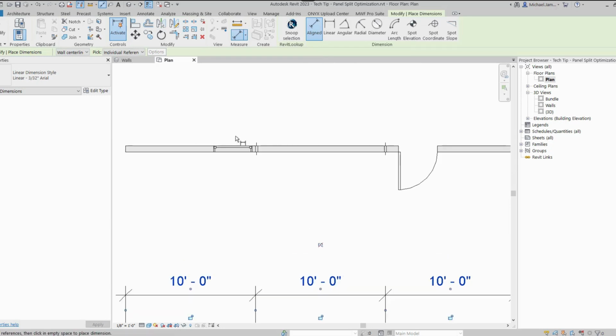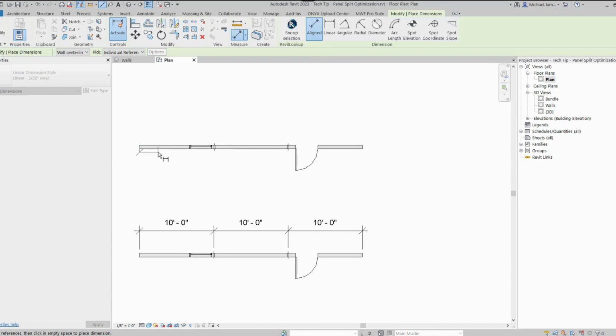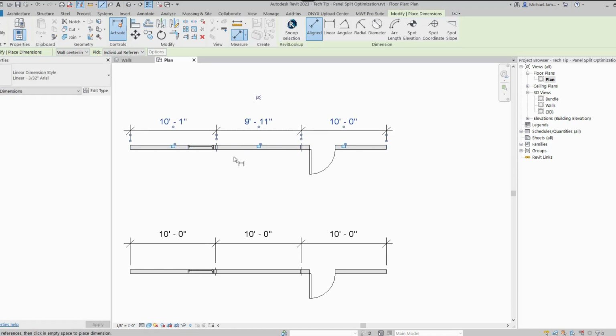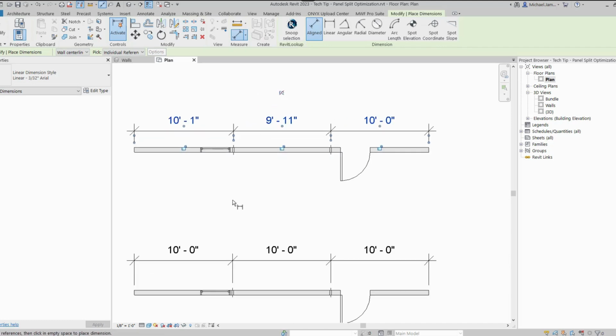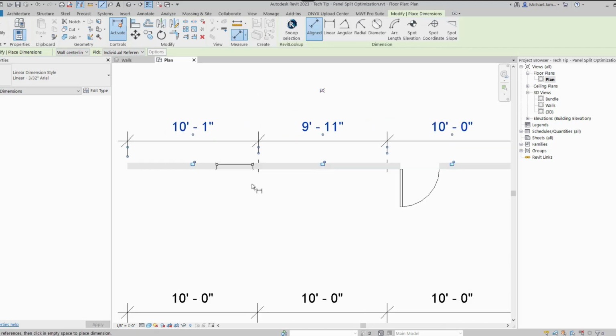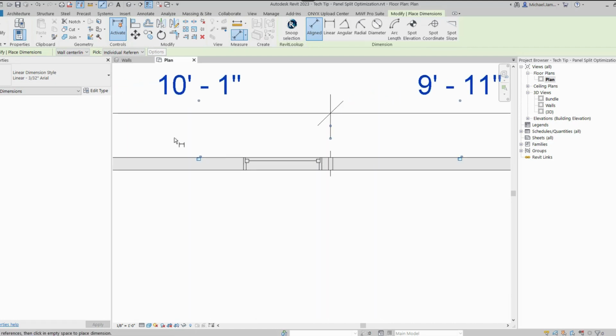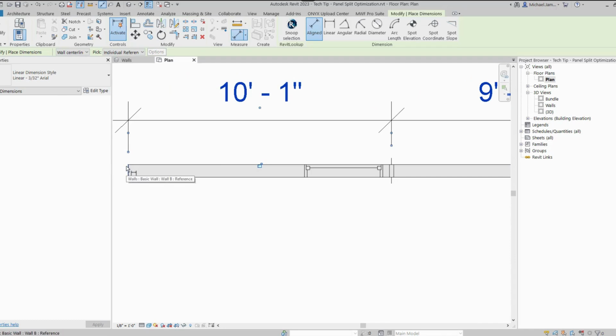For wall B, you'll notice if we measure, because wall B was placed from the end of the panel to the start, that we need to measure from the end this time. You'll notice this time, the split markers have been placed, but they haven't been placed evenly or in the same manner that they have been placed for wall A. This time, wall B has had to take into consideration the location of the opening from the edge of the panel.